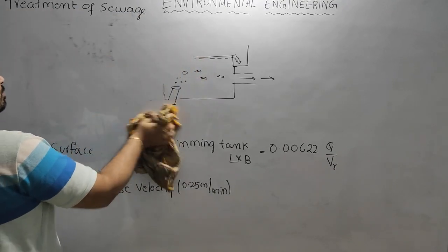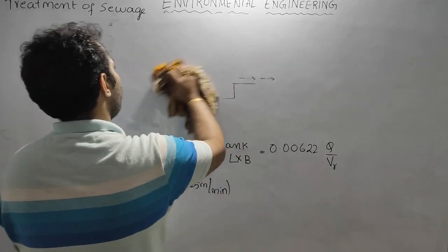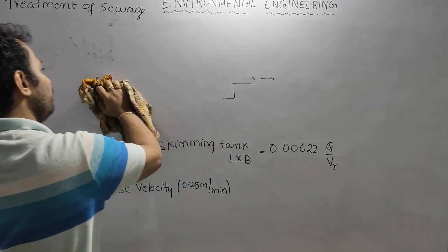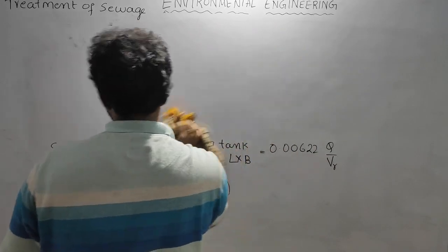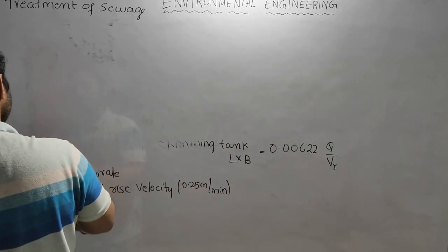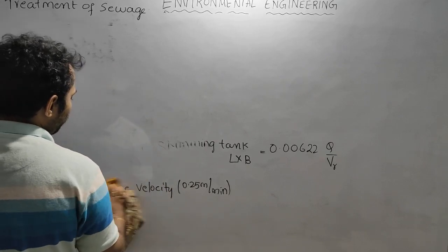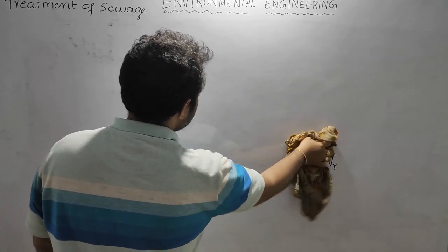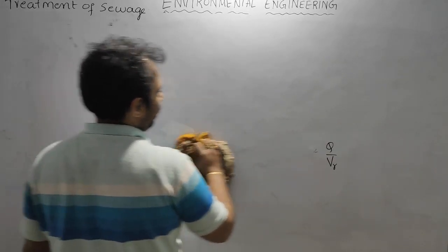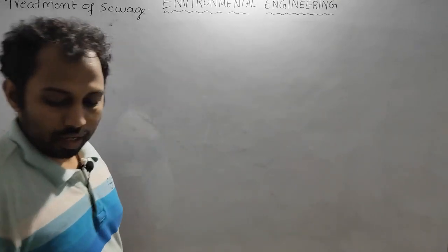Generally sedimentation is of different kinds. In water supply we have seen the type 1 settling tank. Why do we call it a type 1 settling tank? Because type 1 settling has discrete settling. What is meant by discrete settling? It means that when a particle settles, it will not disturb the path of the other particles. That is nothing but discrete settling.